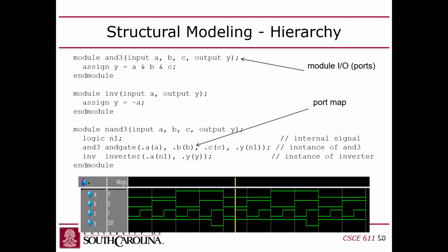Okay, so this is a screenshot of a simulation. Now, notice a simulation is a waveform. So the inputs and the outputs are shown on the waveform, and this is a plot where the x-axis is time and the y-axis is the signals. Yes. Can you perturb the inputs? Yes, you can. You can drive the inputs in the simulator. It's not the way you're supposed to do it. You're supposed to create a test bench, which we're going to do in the next lab.